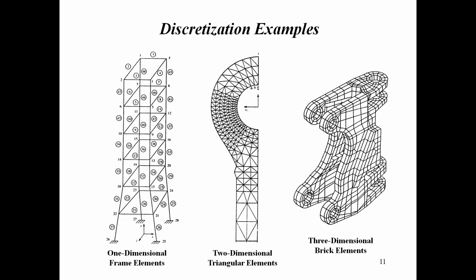And obviously it's a 3D object, so therefore we need to use the 3D element. Here it is also the same. If the structure is irregular, you should use the tetrahedral element, and if the structure is regular, you should use the hexahedral element. But please take note that the results of hexahedral or quadrilateral elements are the best.